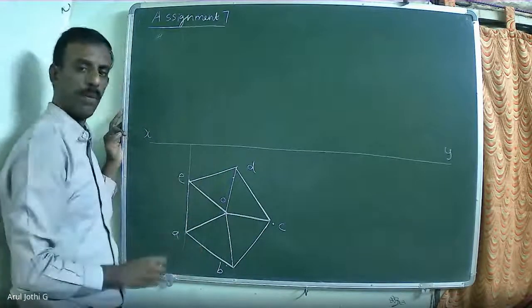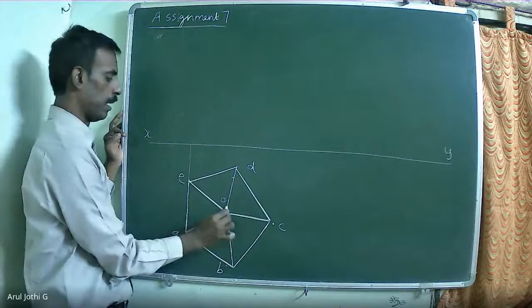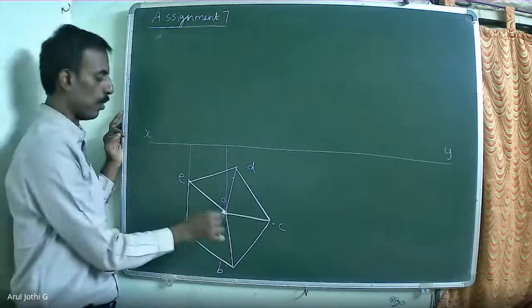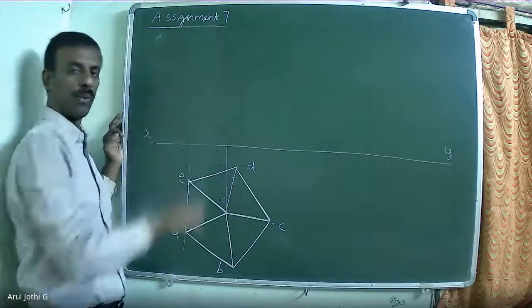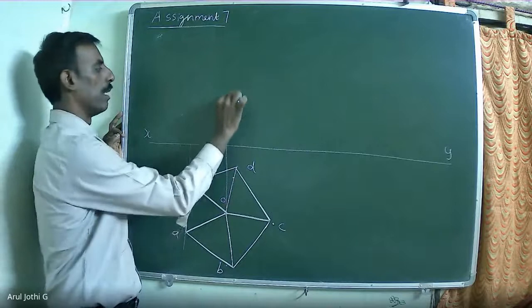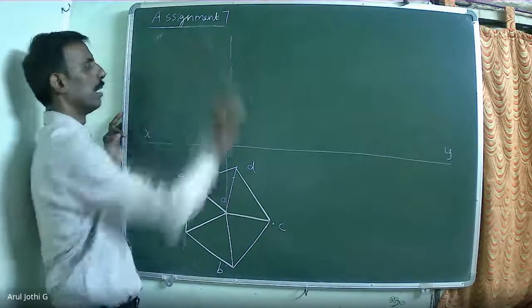how to draw the front view for the pyramid? First, extend the axis line. You have to extend through using the axis line only. Then you are able to draw the front view. Axis height is given as 70 mm. Draw the 70 mm vertical line.